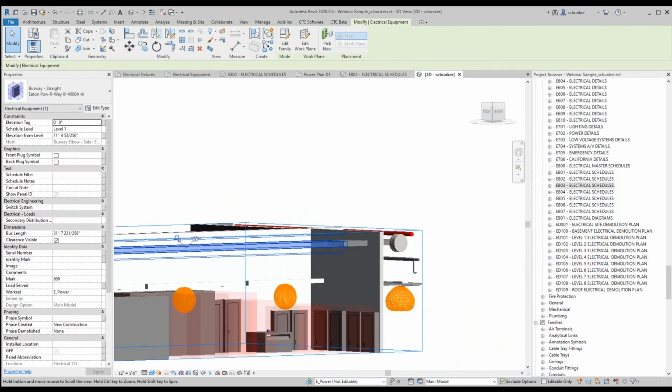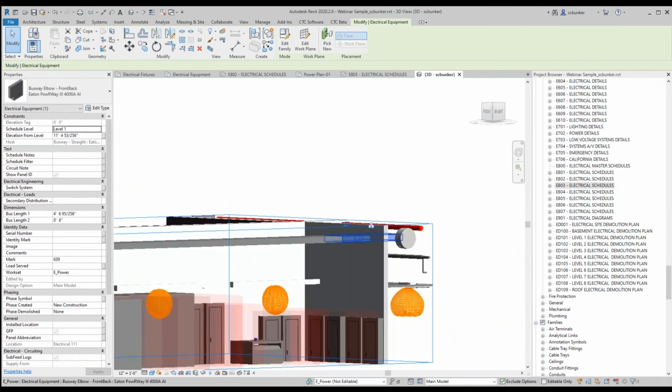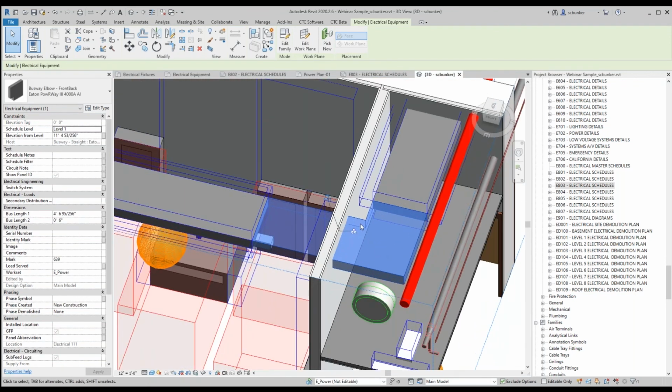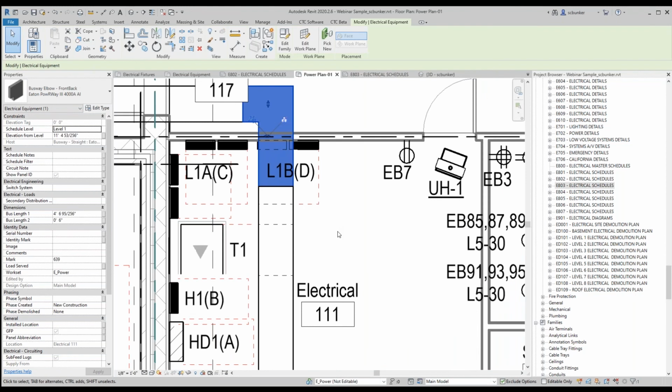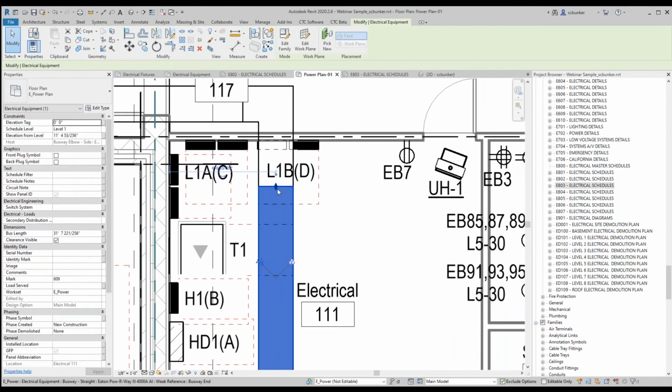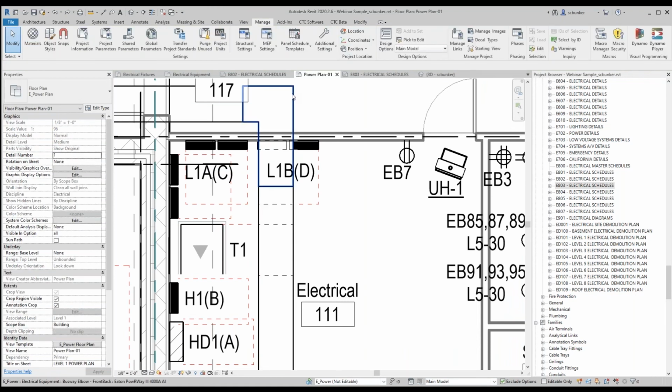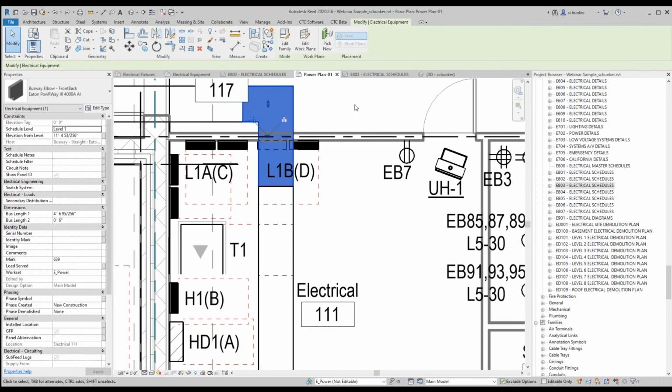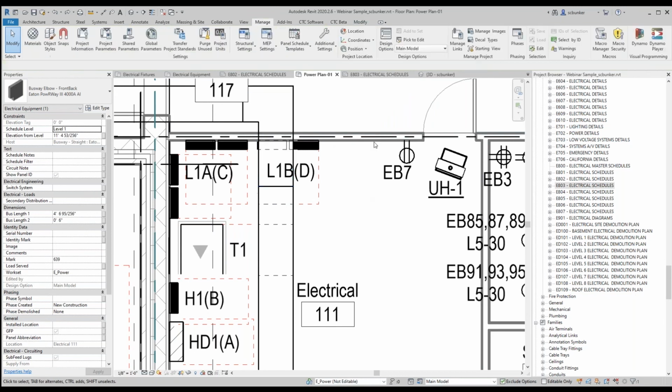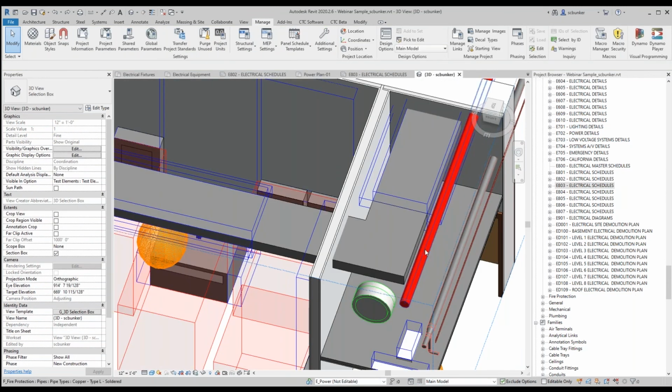That is helpful. Here we go through a wall, we turn the elbow. The length of the two legs of the elbow is adjustable via a grip. So same thing here, all of these things are done by grips. See, I can expand that grip out. And the elbows also, you can change the grip. So if you need to have an elbow right next to a wall, you can't connect the busway in a wall. You have to order an elbow that has one leg longer that'll go through the wall. And so you can do that here.